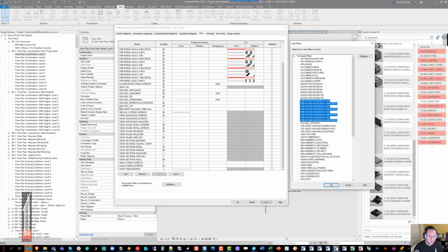We have a filter that's called Include Me in Site Plans, and unlike some of the includes that we discussed earlier, Include in Site Plan is actually an instance property of many items in the template. That's because there may be a staircase that you want to show in a site plan, but it may not be its own stair type. Similarly, there may be retaining walls that you want to show in the site plan, but you don't want to have specific types of walls for that.